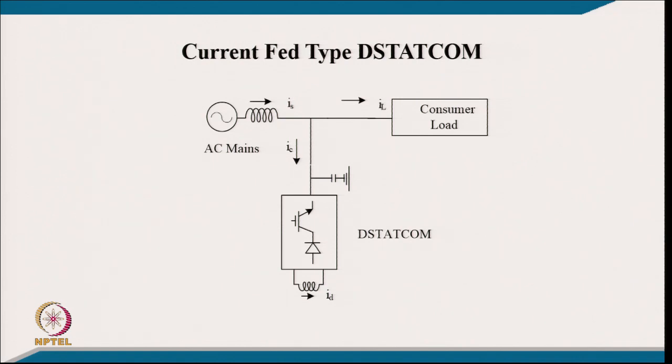And on the DC link side you require energy storage like a current source. That can be realized with the help of an inductor across the DC link. The current in the inductor can be controlled in a self control manner, as we do with self controlled voltage for the case of a shunt compensator. Here the problem is that the output of this converter generates PWM current, which is a segment of the DC link current, and to make this current continuous, we need shunt capacitors, which are mandatory in that case.